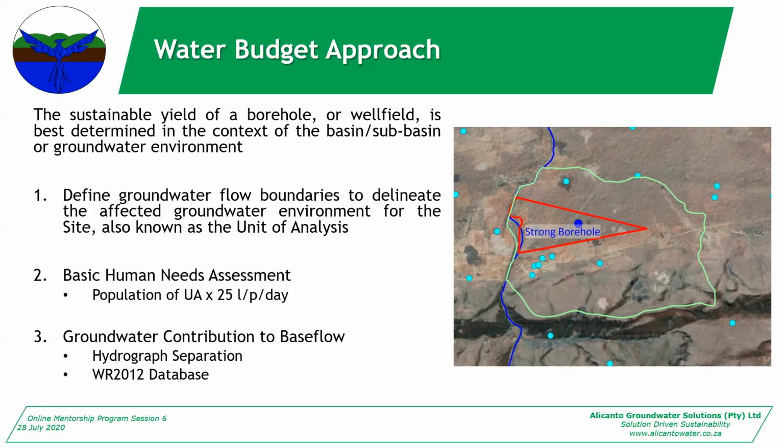It's environment specific. On this one, we had a non-perennial channel here and a geological contact. So you've got a hard quartzite here and then a sandstone here. So it's unlikely that huge amounts of water are going to go through into the quartzite from the sandstone.